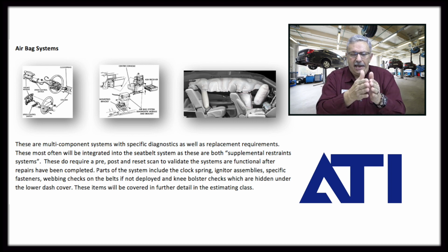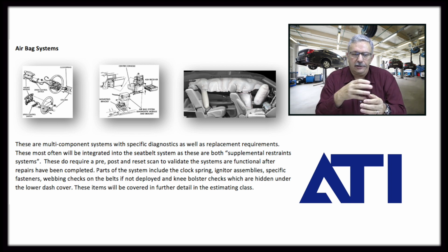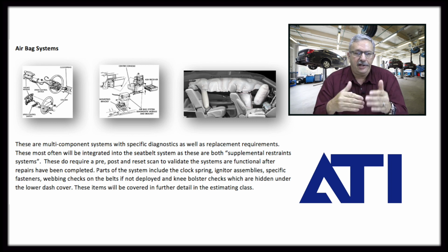The reason being, it directs how the airbag comes out. So if it's loose, it's in less than a millimeter. These are fractions of millimeters that these parts are moving. It will change the deployment characteristics, so it's really important. And we need to check and make sure that if they are one-time only fasteners, that we replace them.